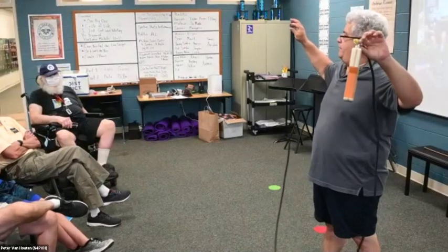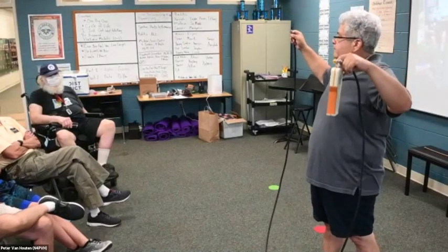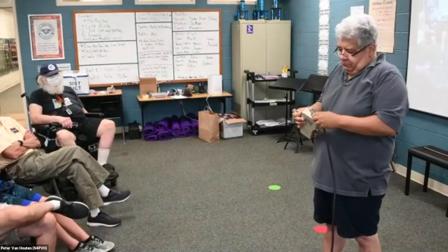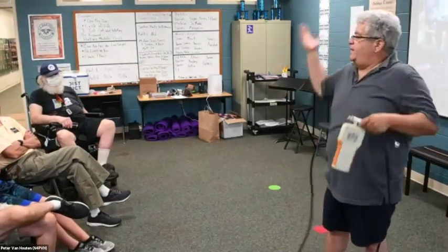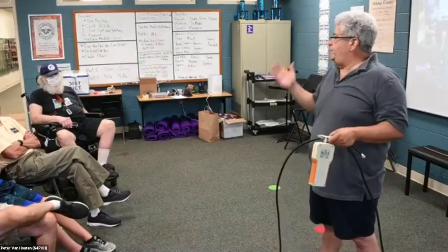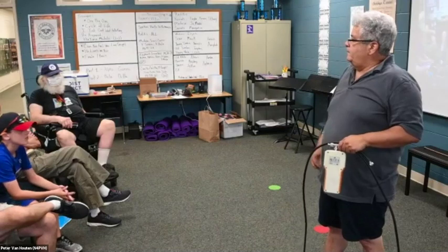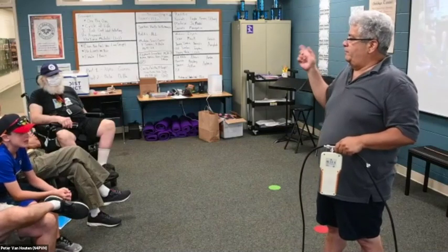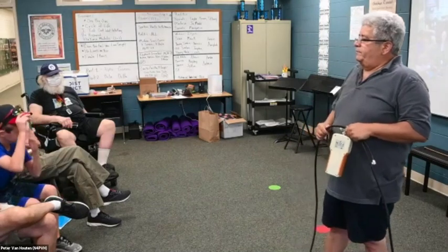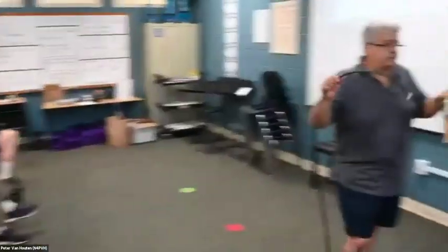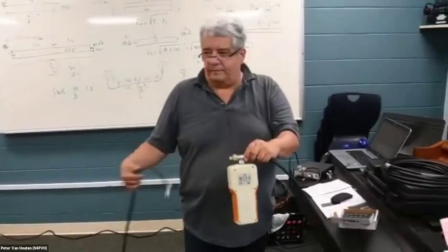And with this method, you can do any length, not only 90 degrees or a quarter wave. You can do any other type of line. Let's say 84 degrees, which is a little bit shorter than a quarter wave. You could do that instead of 90 degrees, simply applying a little bit of inverse proportion. You should try this maybe sometime.